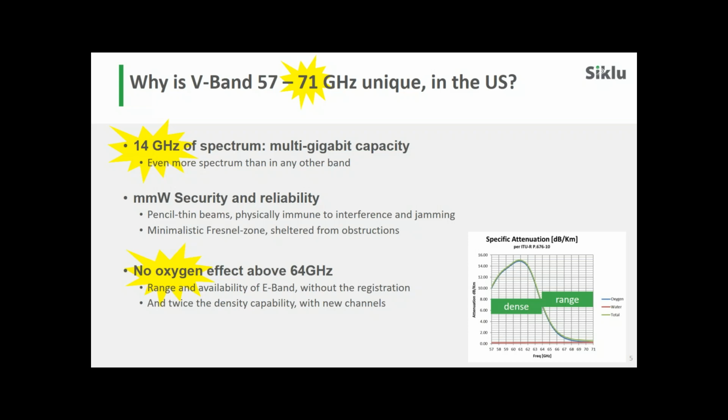If you need all the 3 ports to be available, we have another accessory, a little more complex, where you wire your 48 volt DC, 100 watts or so, into this accessory. This accessory is also an Ethernet pass-through, so all the 3 ports are active. You connect this device on the Ethernet cable going into ETH-1, and now ETH-1 is a real Ethernet port, and that accessory that we have on our price book makes it possible to wire direct DC into ETH-1 at the same time as ETH-1 is a fully functional Ethernet port.